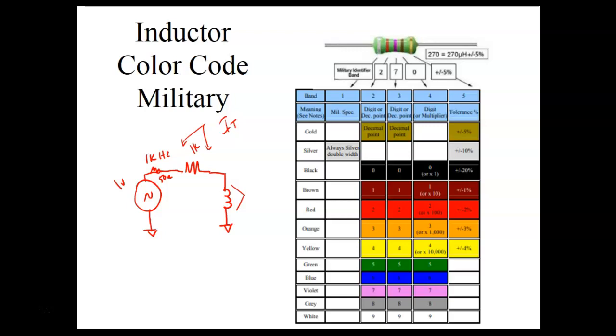That's one of the reasons why the cable lengths are limited. Ethernet is 100 meters. If you go over 100 meters, you have to go through some type of repeater, because now you're dealing with the resistance of the cable. So that's 50 ohms, so I could play around with a 50 ohm coax cable with this function generator, and I would have impedance matching. If I was testing out a coax system, but it wouldn't work on the Ethernet cable because that's a 100 ohm cable at 100 megahertz.